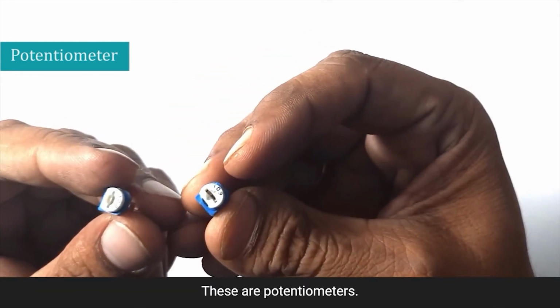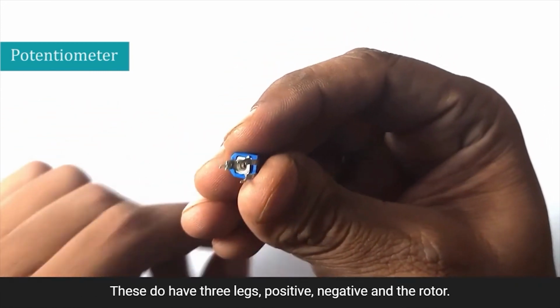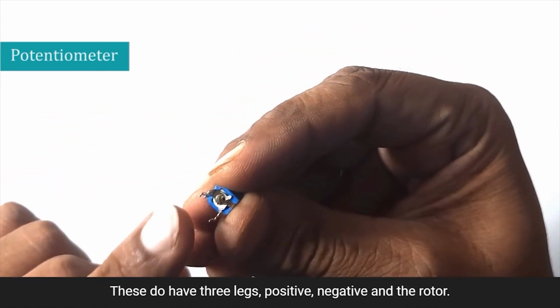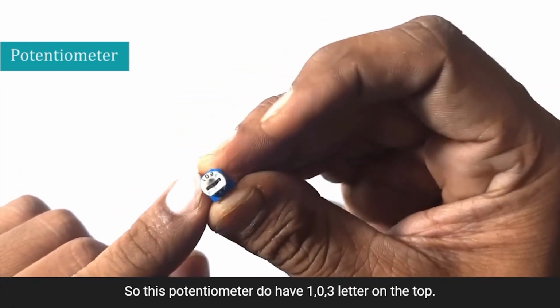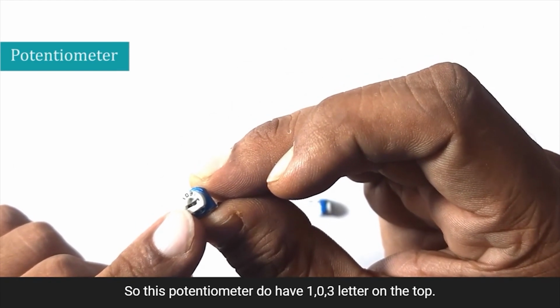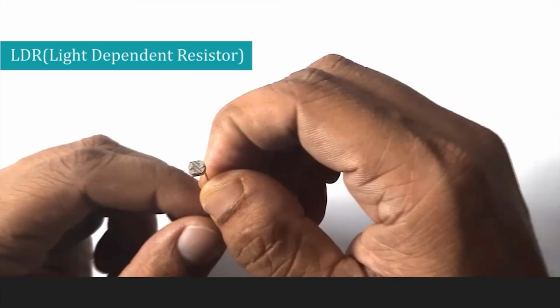These are potentiometers, also called variable resistance. These have three legs, positive, negative and the rotor. It changes the resistance value. So this potentiometer has 103 written on the top. It means that it has 10 to the power 3, that is 10K, resistance.